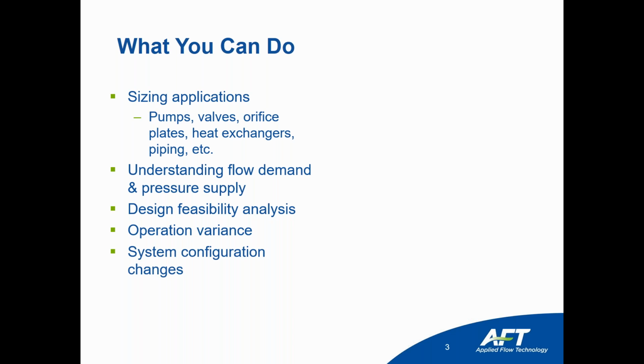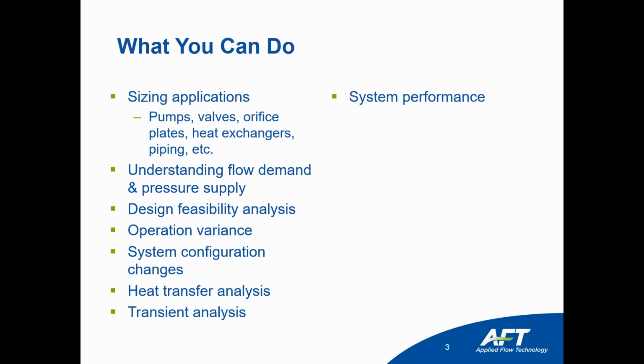You can easily model different system configurations very quickly. You can do a full heat transfer analysis. You can do transient analysis. With pumps, you can model your pumps changing their operation over time, either with changes in speed or changes in their flow set points. There's a lot of flexibility available to you there. You can model your system performance and make sure that you're operating close to your best efficiency points.